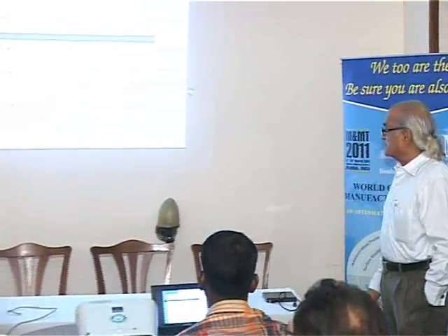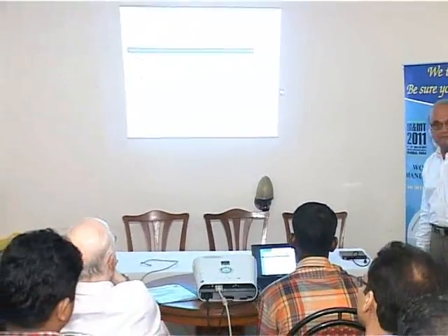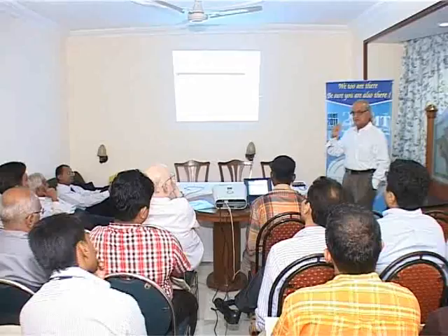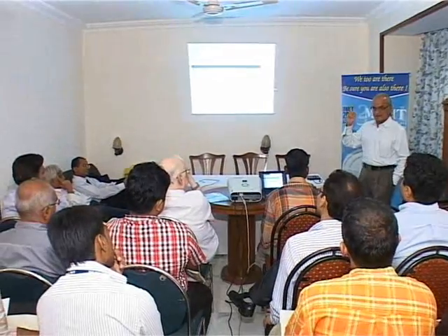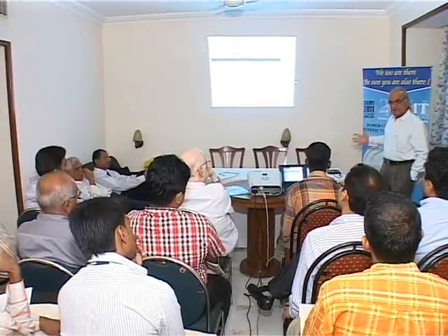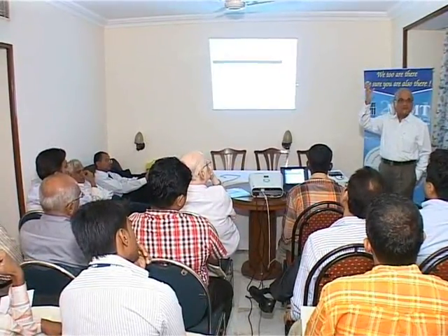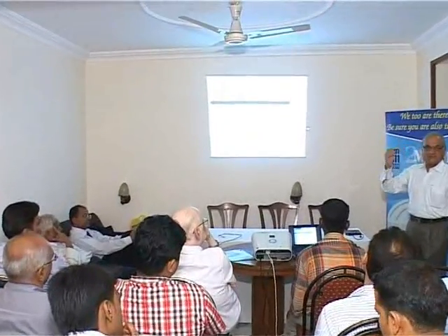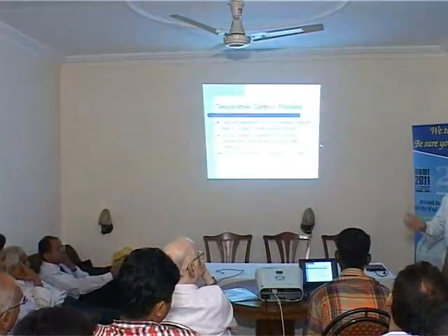Next. Yeah, this is what I was talking of. A typical on-off controller. At a particular set point, 925 degrees, you have set there, it trips off faithfully. It does. But then the initial heating power in your heating elements boosts the furnace, continues to heat it up another 5 or 10 degrees, which is called hysteresis in the instrumentation language.